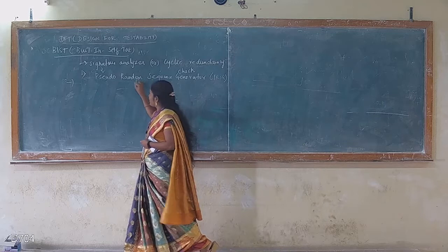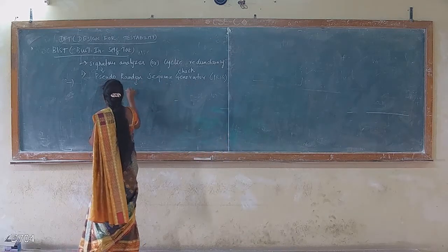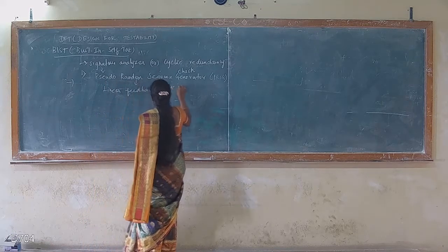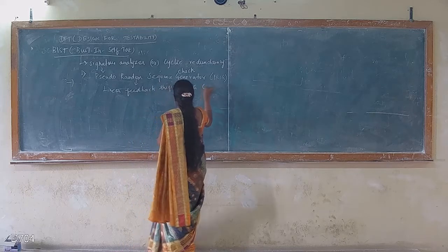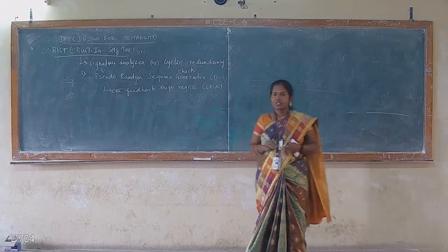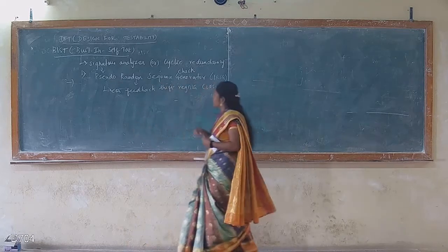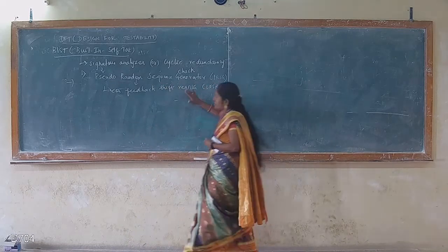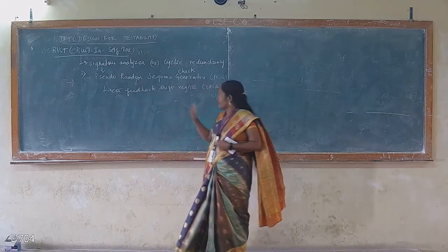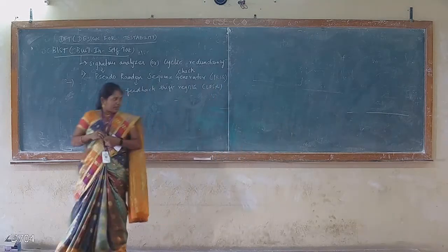This can be constructed using a linear feedback shift register, LFSR. A linear feedback shift register is nothing but a simple shift register with feedback from two or more outputs to the input. This can be constructed using flip-flops. For an n-bit shift register, we need to connect n number of flip-flops and the XOR gate.